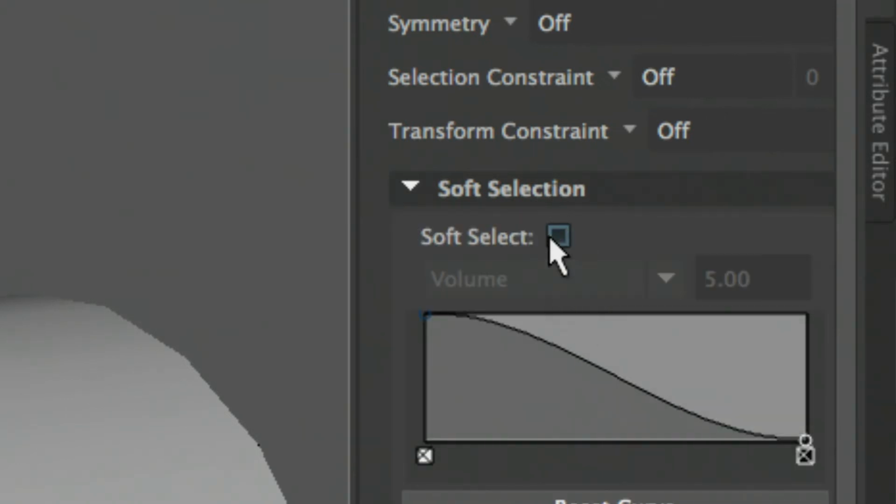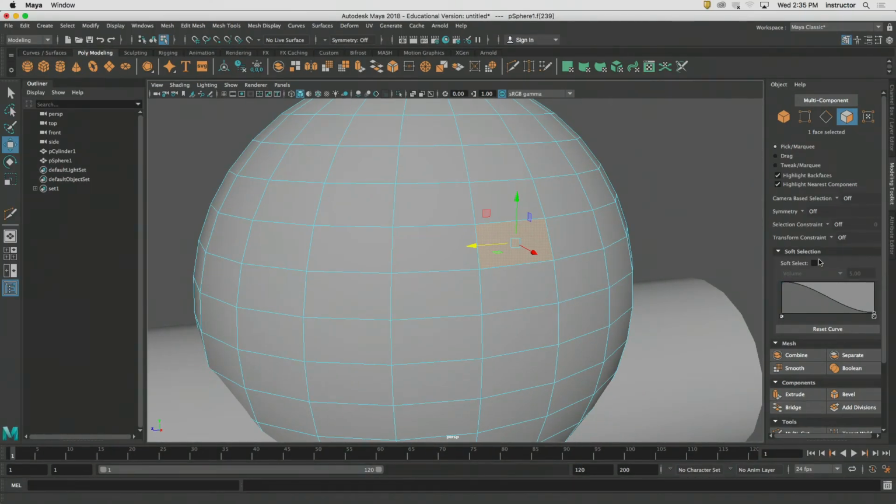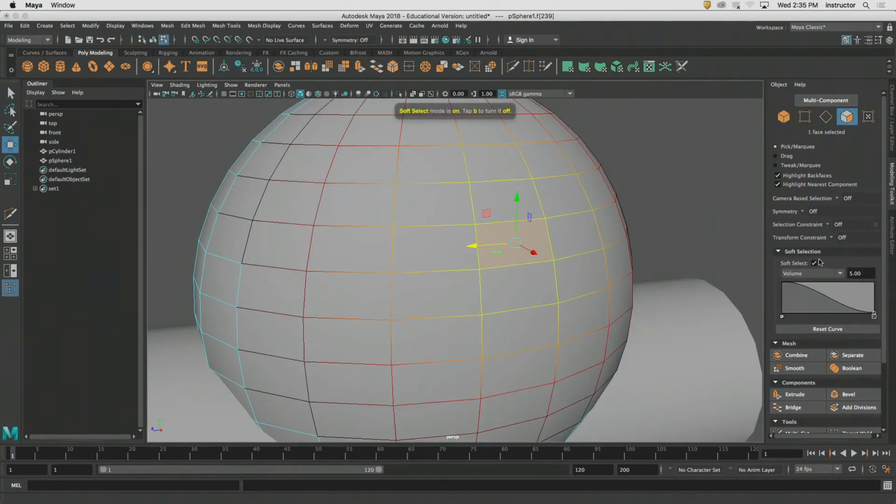Okay, or there's a keyboard shortcut, and this is an important keyboard shortcut to remember because you're gonna bump it on accident. Okay, and it's the B key. B as in boy or Bravo. Okay, and you're gonna go, what is going on? Why is my mesh all these multicolors now and nothing is working the way that it worked 2 seconds before? WTF, panic, run out of the building screaming, right?